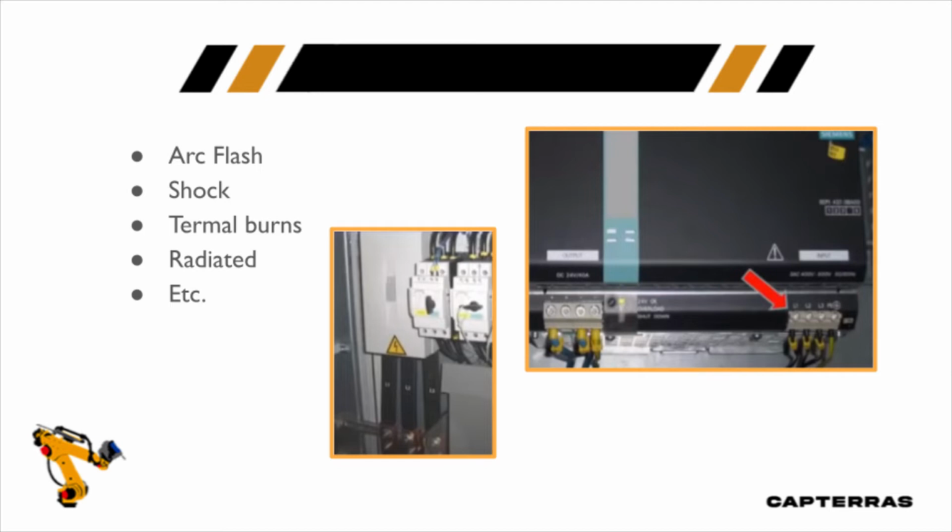A lot of times when we get into equipment, we think of arc flash as being at the face and chest. Maybe I have 1 calorie at 18 inches working distance from where I'm working. So I may not have to wear any arc-rated clothing on my body because we're looking at the 18-inch working distance. Yet my hands, even with gloves on, and part of my arm may be much closer. It's 1 calorie at my chest, but what is it at my arm? I'll have a slide coming up where we'll talk about that further.